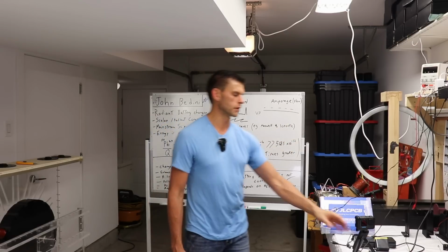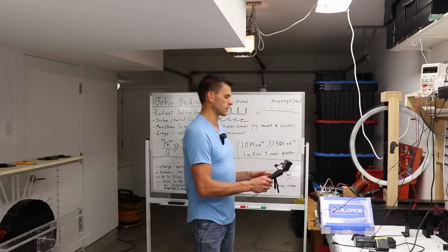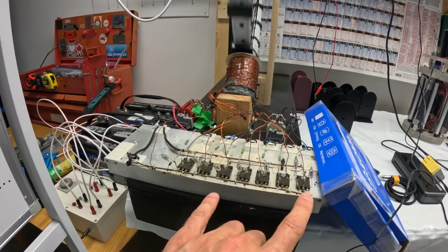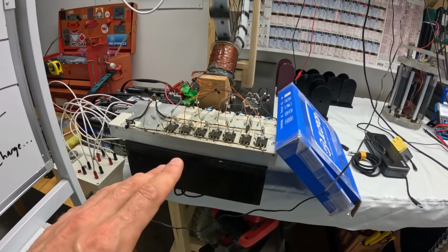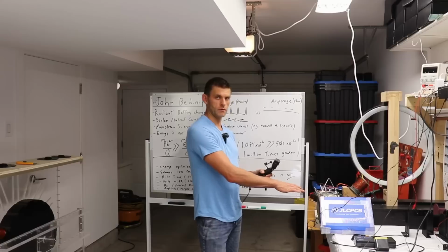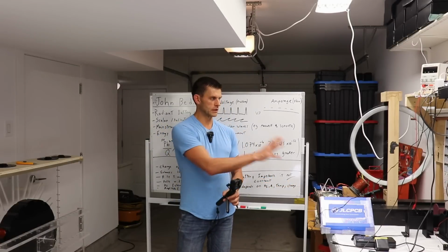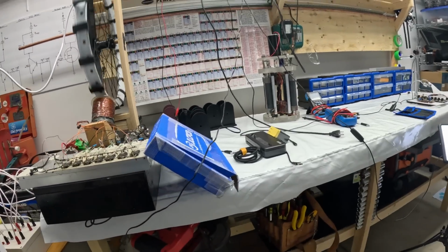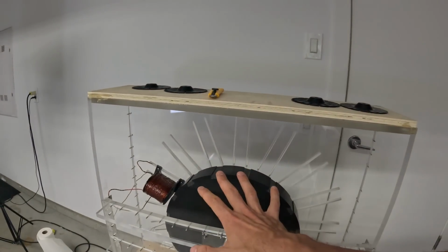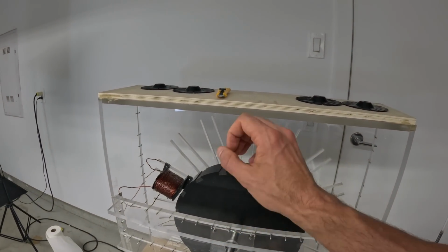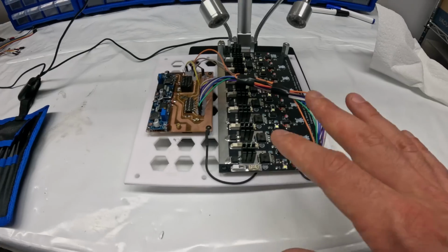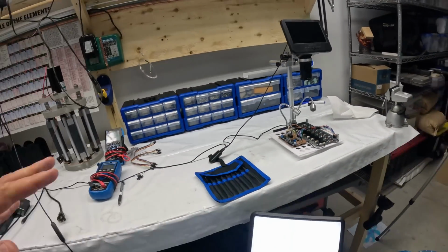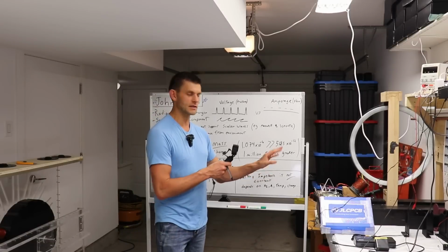So this particular motor, the Bedini motor, was built back in the day when these types of switches, which are called transistors, were economically viable. These particular ones are BJT transistors. The main difference between this device and our device here is the switching tech. The transistors used on this one here are not BJT transistors. They're MOSFETs or FETs, N-channel FETs. And all you need to know about this is basically these switches here.